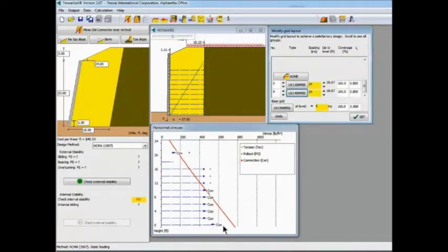and in this case it notes that it's failing in CON, which if you look at our key here is connection. So these geogrids here are failing in connection, the next 3 are satisfactory, and then we have a couple of grids that are failing connection and are non-existent. We haven't filled in all the geogrids to the top of the wall yet, as you can see in our cross section. So the first thing to do would be to add geogrids up to the top of the wall.